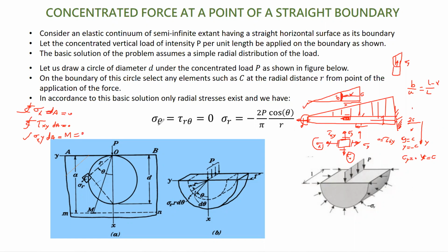This is the way we satisfy the boundary conditions at the two ends of the beam. If there was a shear at the end, that integration should give you the shear. If nothing, it is 0. If there was an axial load here at the end, P, it should be equal to P. If not, it is equal to 0.